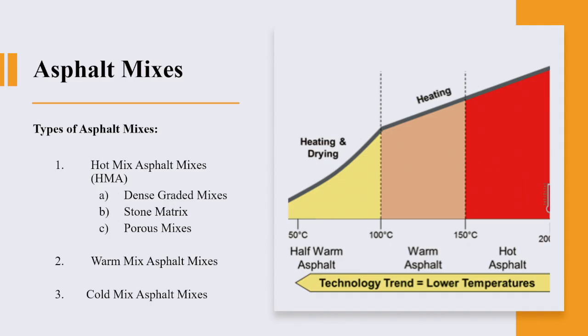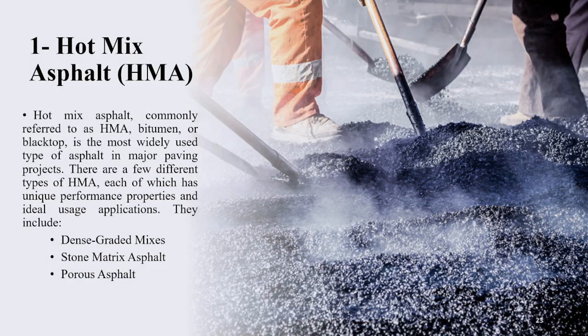I mean, maybe I can understand this in Nigeria because you don't have the. Do you have any cold weather anywhere here in the country? Very limited, right? Yeah. Now, when I teach this course in Bahrain and Qatar and in Dubai, they know what warm mix is, but they predominantly use the hot mix because basically there is no much need for reducing the temperature of production. And hot mix will be cheaper because in order to compensate for the difference in temperature you have to use emulsions and additions to make the asphalt as flexible under lower temperature as it is for the high temperature or hot mix asphalt.